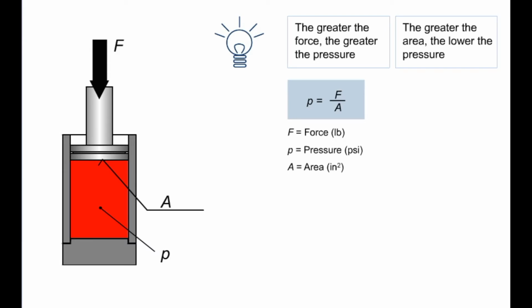This relationship provides us with a formula to calculate static pressure. Pressure is the ratio of the force to the applied area. The imperial unit derived from this for pressure is pounds per square inch, or in short, PSI. 1 pound force acting on 1 square inch of area will produce 1 psi. The derived SI unit of pressure is the Pascal, or Pa. Blaise Pascal, a great philosopher and scientist, was the first person to undertake intensive studies of hydrostatics. In practice, the unit, bar, is generally used in the metric system to express values of pressure. 1 bar corresponds to 14.5 psi.